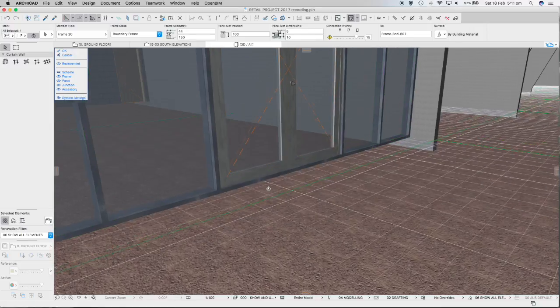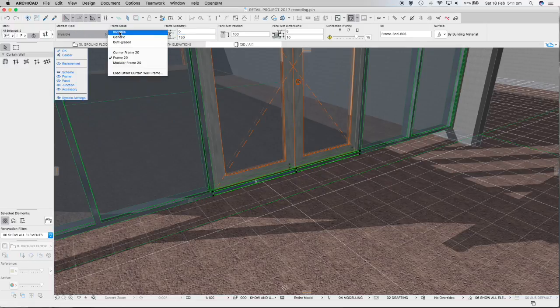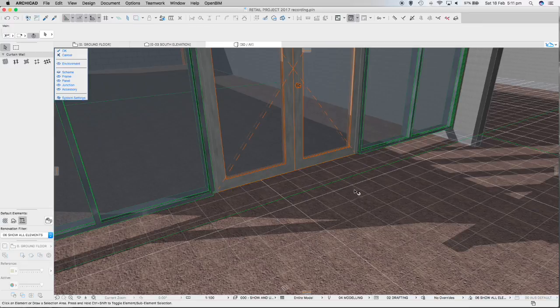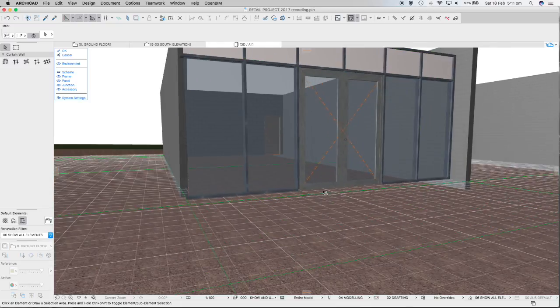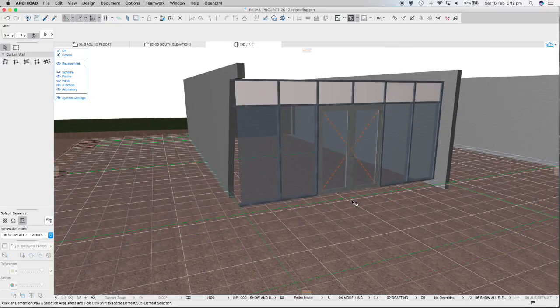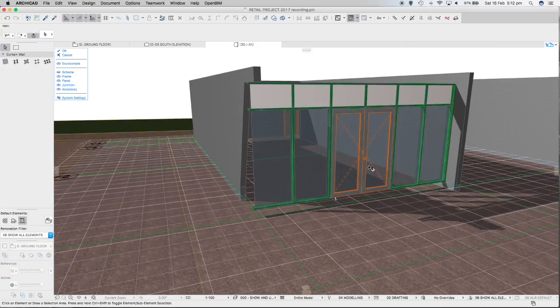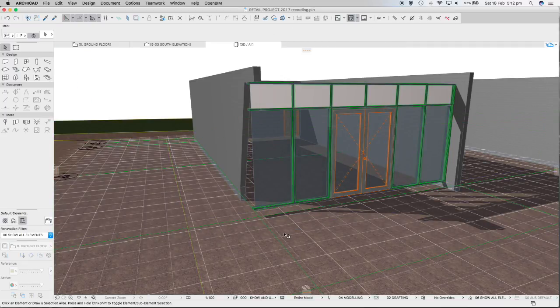It's a boundary panel, and I think you can't delete boundary panels. But what we can do is select both of them, shift select both of them, change its thickness once again to 0, and change its member type to invisible. Right, there we go. And that just readjusts that panel, so now the door sill swings down without a frame at the sill level. It can go straight down to the floor coverings. So over here, you can then click OK, finish that, and that's that curtain wall finalised.